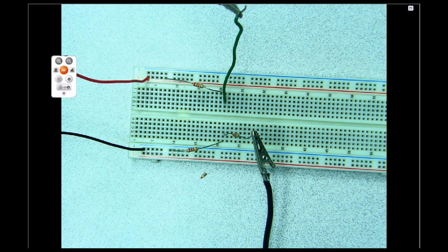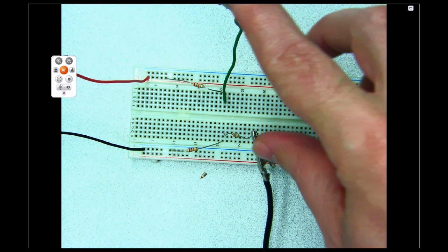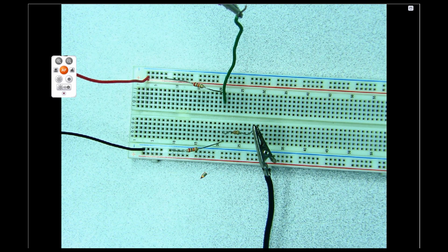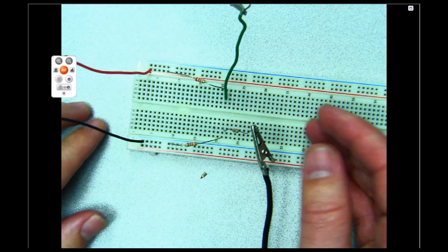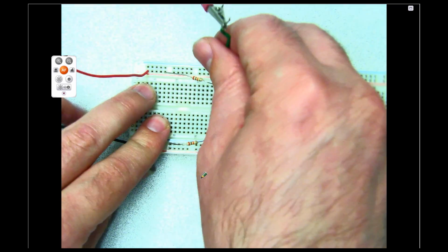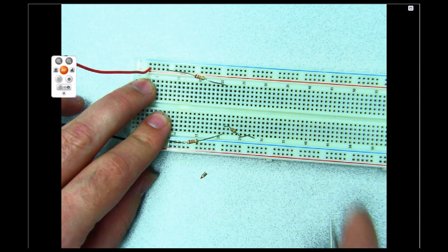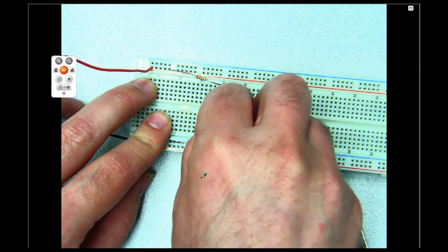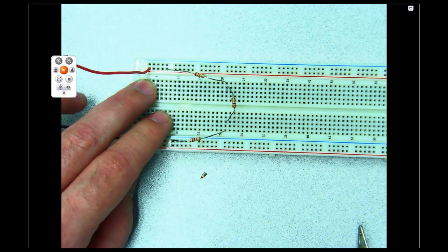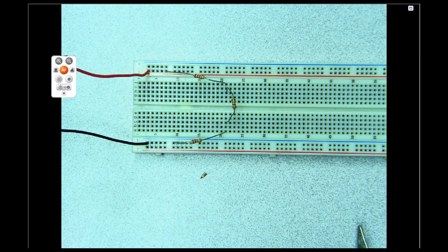And that's what you want. That's how you measure that current, okay? So you break the circuit apart, you create these two loose ends, you connect the loose ends to your meter, you measure your current. And then after you're done with that, you put everything back the way it started. So you pull out this wire, you disconnect your meter, you plug your resistor back in where it used to be, and now you're ready to go on and make your next measurement or do whatever is next part of the lab, okay?